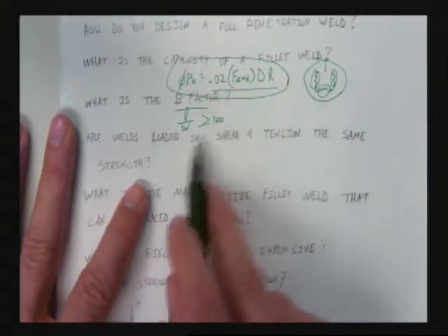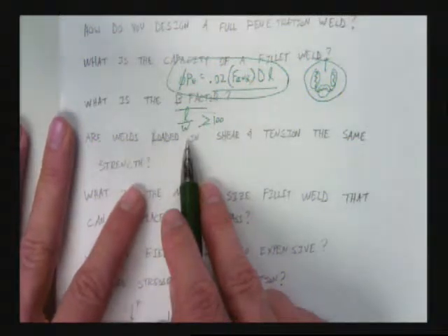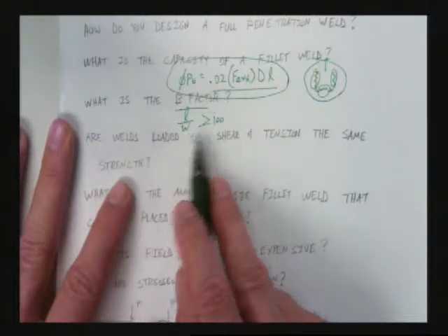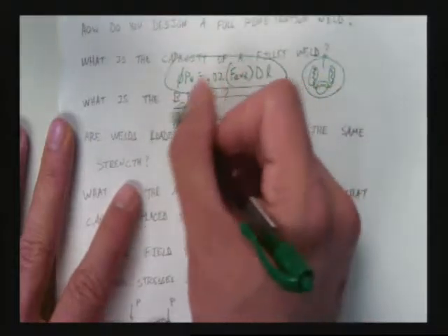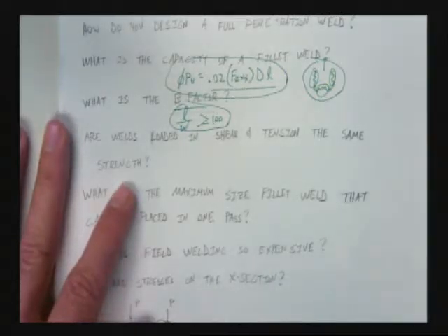So that means if I have a half-inch weld, which doesn't ever happen very often, it would have to be 50 inches long, right? So this needs to be something you have built into your steel DNA. When you see a weld that's really long, you need to start sweating a little bit. Maybe you should be thinking that beta factor might be important.